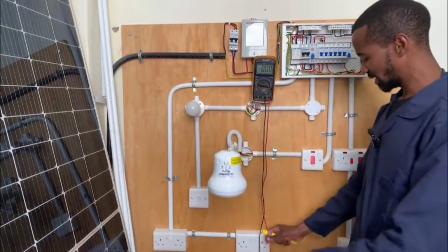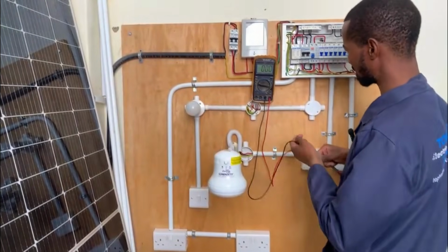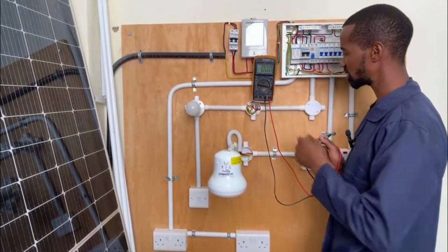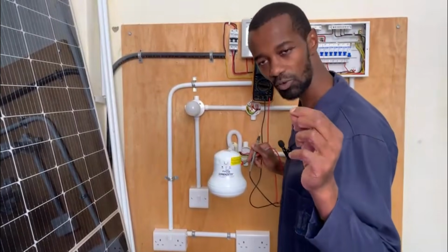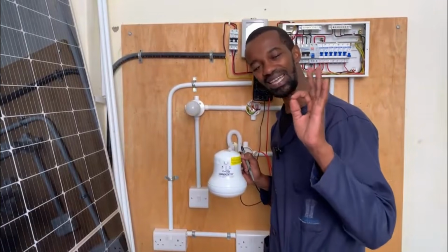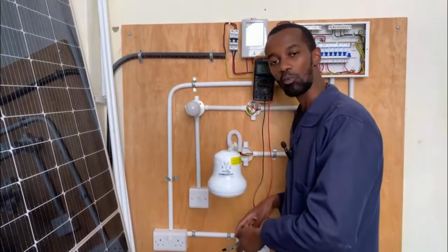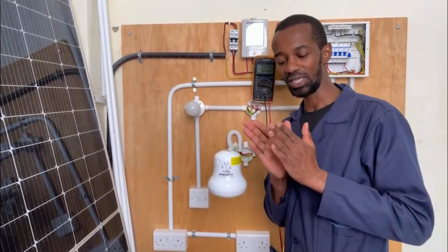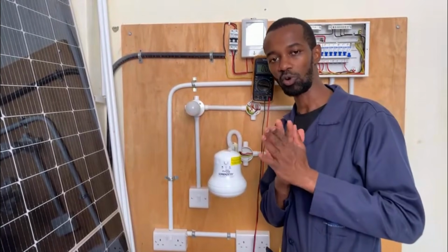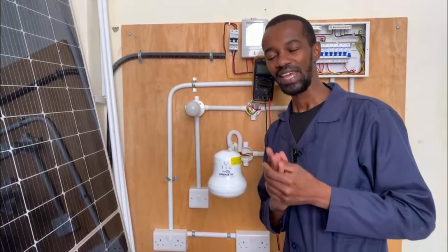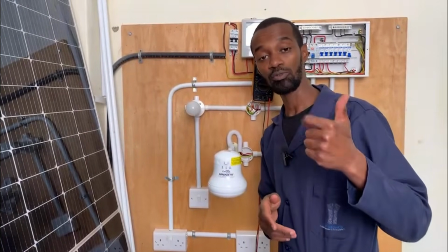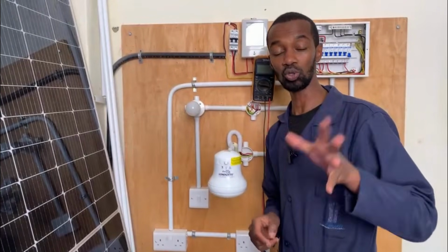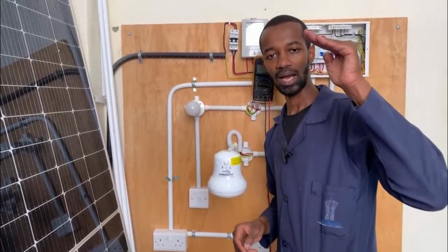Now, what I was saying is, you have a digital multimeter set to AC. We expect a reading of more than 200 volts AC. So we will not place it at 200 volts, even though you were expecting exactly that. For instance, when taking a reading for a 12 volt battery, and your digital multimeter has a position for 12 volts, you don't place it at 12 volts. There are some batteries which are charged up to 14.5 volts. Therefore, you will not get the correct readings. So what you do, you go to the next higher level.